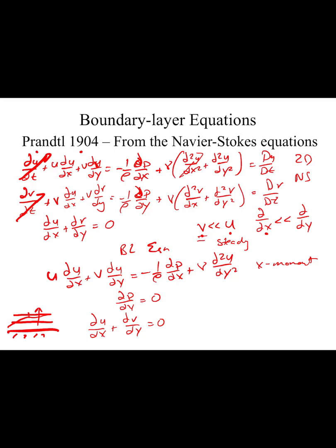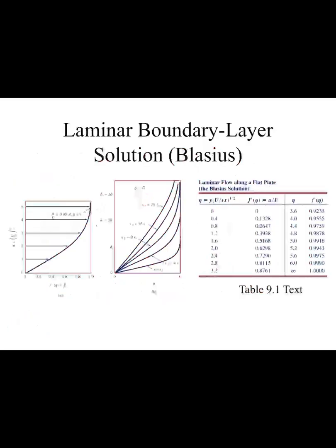And then one of the things that Prandtl focused on after that was the zero pressure gradient boundary layer. So this is a general boundary layer that has a pressure gradient. If there's no pressure gradient, then this term goes to 0, and then we simply have a balance between advection and diffusion. And that's what we talked about before. That's a key part of what a boundary layer is, this balance between advection and diffusion, unless we have a pressure gradient. And in fact, today, that's going to be one of the key things that we're going to talk about.